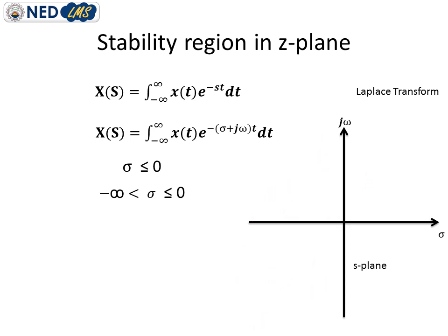But what about the Z plane, as it is basically the polar representation of complex frequency? So the radius r is equal to e raised to power sigma, as calculated in the previous slide. So we have two limits of sigma here, minus infinity, and the extreme limit is 0. We cannot move beyond 0 because after this value the system will become unstable.